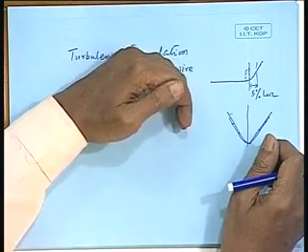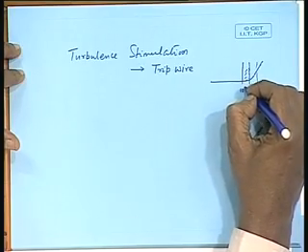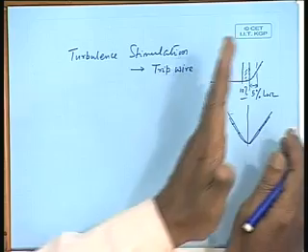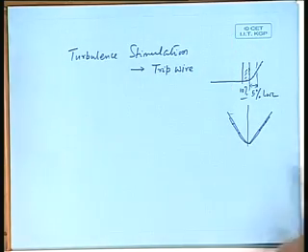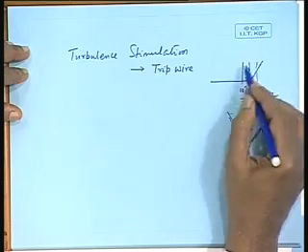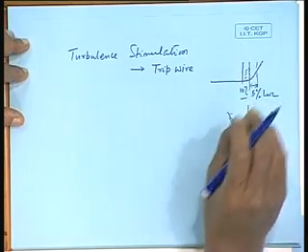So, the turbulence that you created may be suppressed again and laminar flow may take over. So, it is common practice to use not only one, but maybe 2 tripwires, another at maybe 10% distance or 7.5% after, it depends on the type of model, type of fullness, etc. So, this is how the turbulence is stimulated.